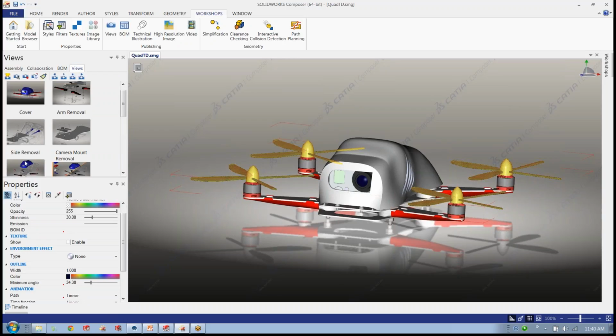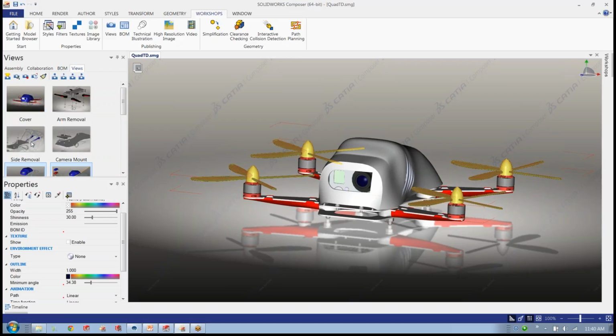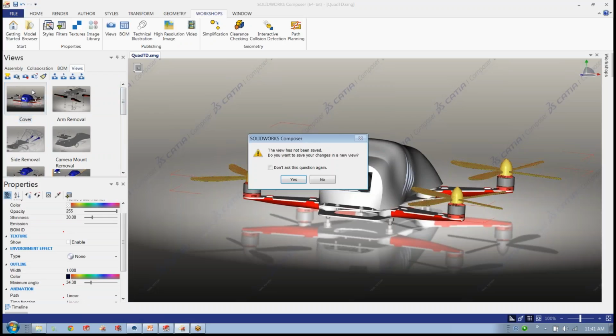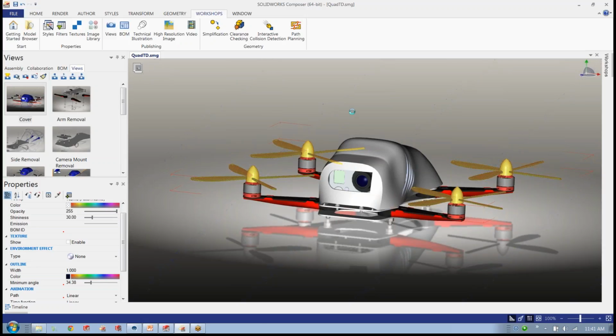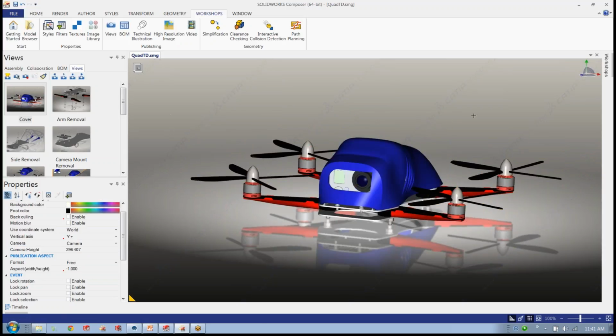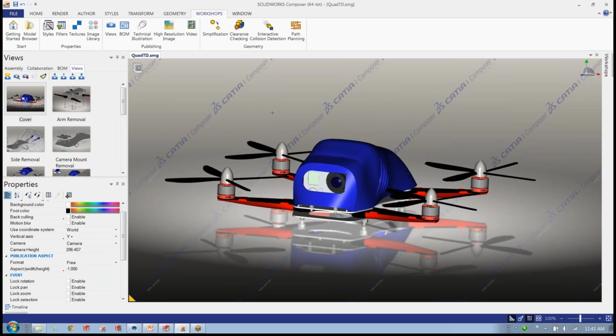So anywhere I want those 4-blade propellers to show up, I'm simply going to select those existing views. I just held down the Shift key there to click all those views, and I'll hold the Control key to collect this last view. And I'm going to use the shortcut here to update all views with selected actors. Any views that I've selected are now going to include any actors that were selected in the viewport. So let's go ahead and cycle through these views. We can see now that our cover image is updated. If you need to change the position or anything like that, simple to do just with the mouse wheel. We'll go ahead and update our view.